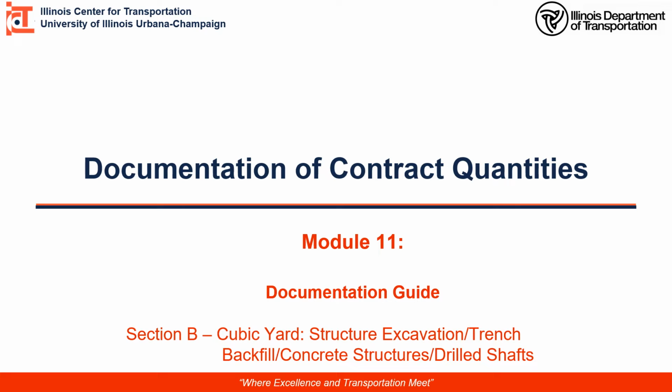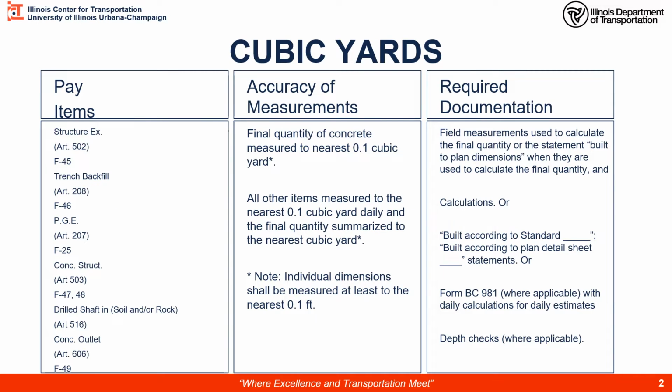This is Module 11, where we will cover cubic yard as a pay item for structural excavation, trench backfill, structural concrete, and drilled shafts. On the doc guide, page B as in Bravo, B1, you will find the requirements for cubic yards, accuracy of measurement, and the documentation required.